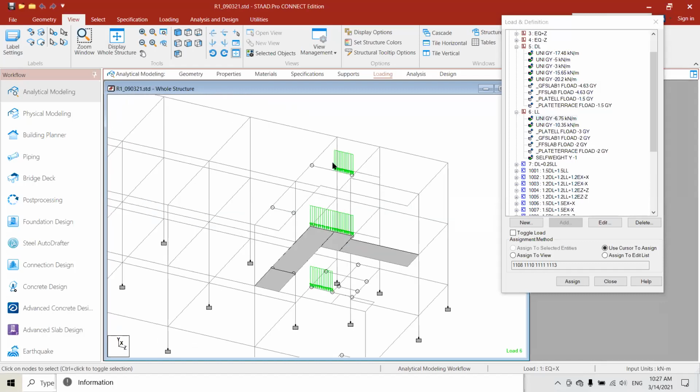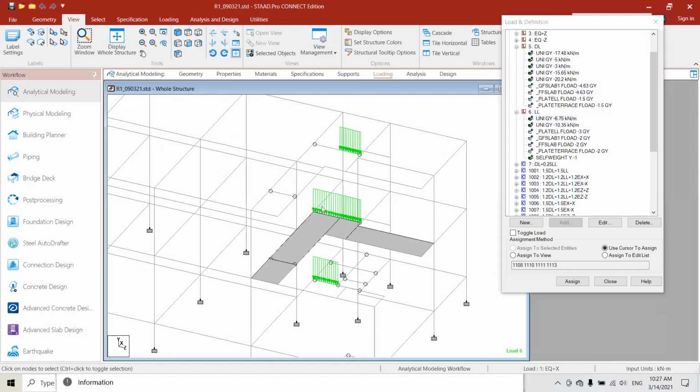See, this is a staircase loading. So it will depend on where your step rests. We need to assign the load only to that particular area. You can see I didn't assign the load for all the area, because the stair spanning is only in this area. If I assign to all area, that means an increase of the reinforcement.